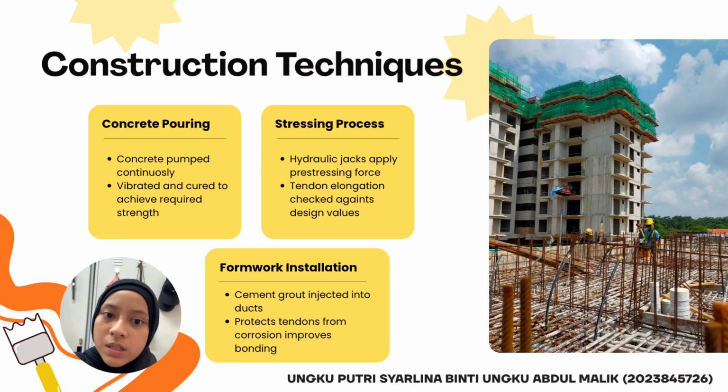to ensure it meets the design requirements. It must follow the structural drawings. And finally, for the grouting, the cement grout is injected into the ducts to protect the tendons from corrosion, and also to improve the bond between the tendons and the concrete. So that's all for the construction techniques.